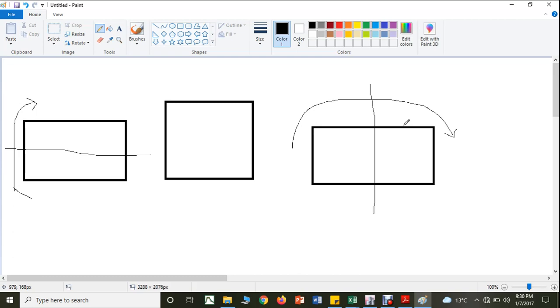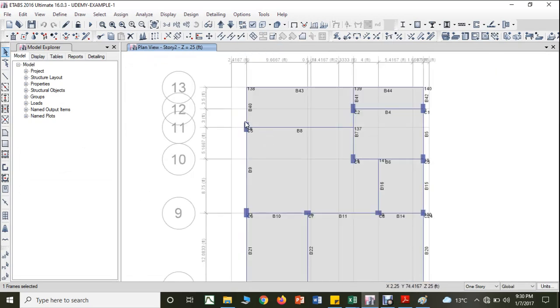Okay, so now for example, let us explain that in the plan. If I take this column, you can see that this is the beam but it is not a main beam. This is not a main beam either, but this is the main beam. Why? You can see that these are connected by the columns. So therefore this acts as the main beam or the mother beam, these two are the secondary beams. So we have oriented the column in such a way that, since this is the main beam, the column will try to bend in this direction like this, that is perpendicular to your longer direction.